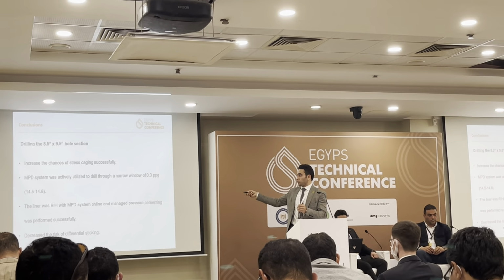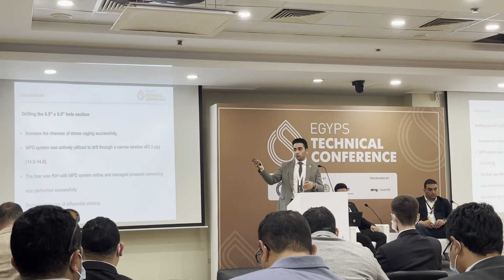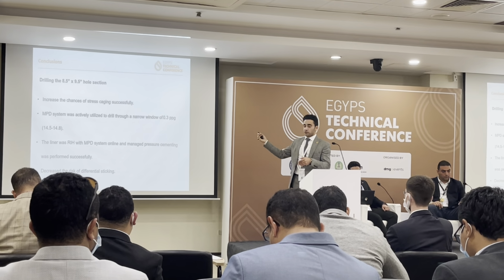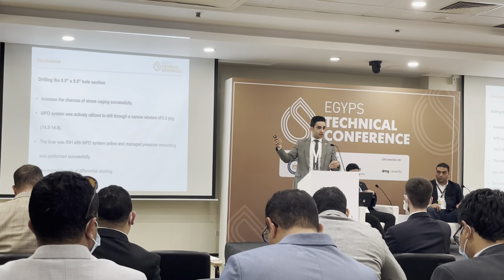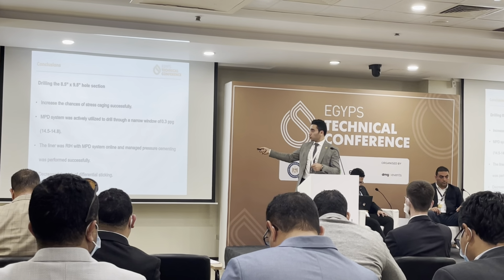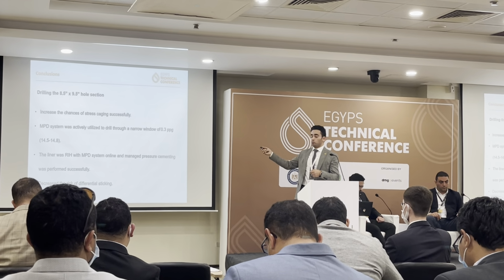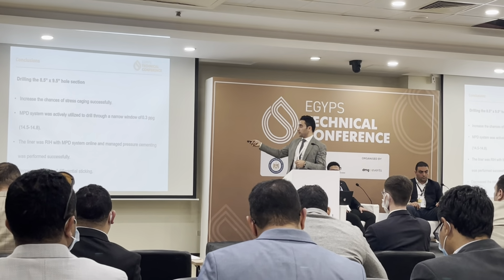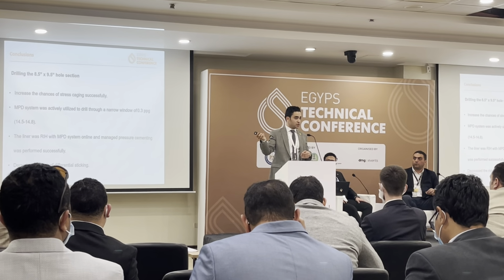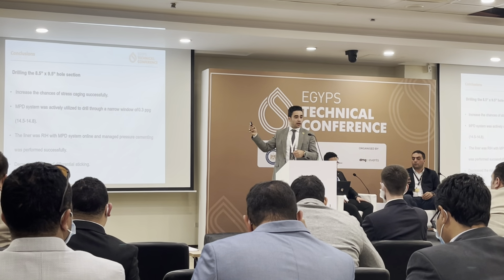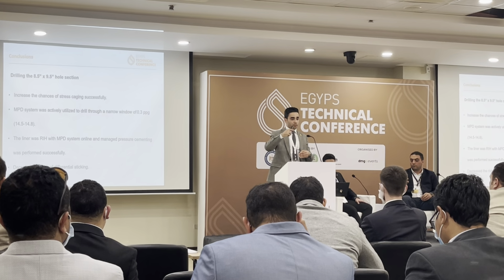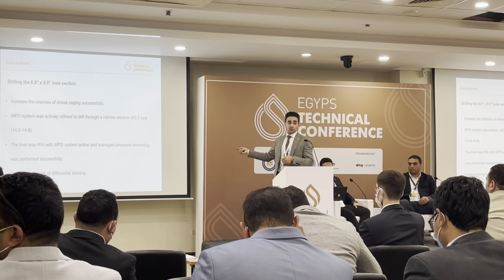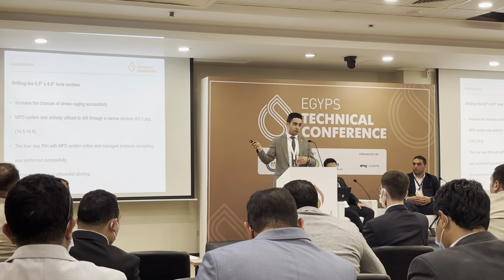Also, with MPD we accomplished, or it enabled us, better zonal isolation, where we used it to run and cement the liner, imposing lower ECD on the formation. And it also decreased the wellbore stability issues and differential sticking, despite the high overbalance between the mud and the depleted reservoir. It was 3,600 psi overbalance.